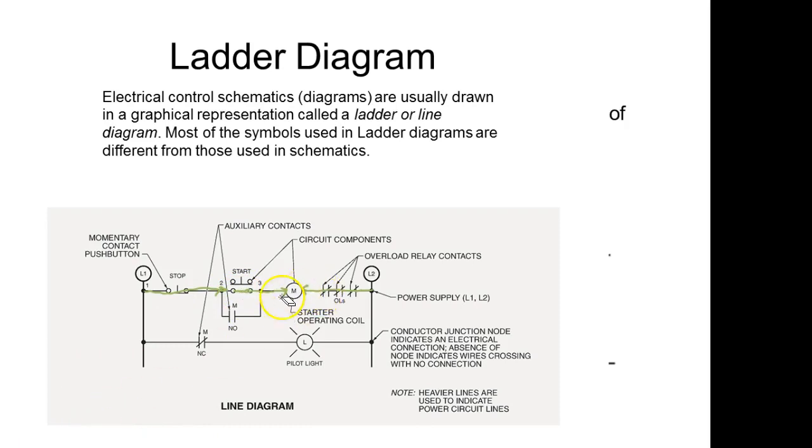But what happens is when this energizes, this contact down here closes, right? You understand that? So now I've got a secondary path. Now I can let go of the start button, and this guy is sealed in. We call that a memory circuit. Some people call it a 3-wire circuit. Some people call it a seal-in circuit. So I hit it, and then I can let it go.